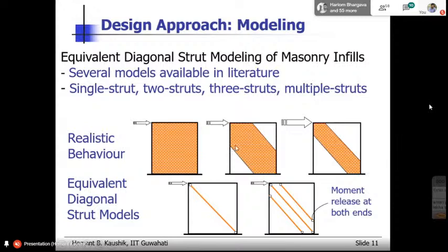There is always a tendency for the column to exhibit some large shear force here, because this part of the wall is under tremendous axial load. So it has to actually transfer that load. So some part of that load, when this lateral load is applied, is actually transferred to the column here. So this beam, this column may not be designed for that load.